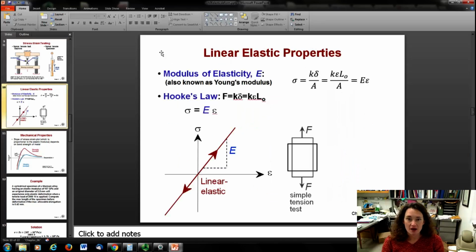All right, like I said, this is a Hooke's law kind of idea. If you're in the linear regime and you haven't begun to permanently deform your material, then you're governed by Hooke's law, which is similar to the force on a spring. So put Hooke's law in terms of some of our symbols that we're using here. The force would be equal to K times delta, where delta is the change in that length, similar to K delta X for Physics 1150, 1151.